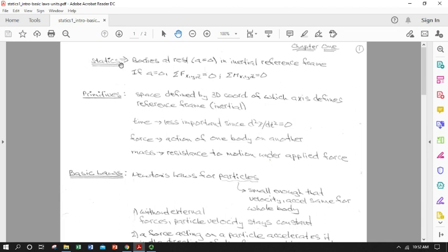Okay, so let's start out with the definition of statics. What is statics? Because engineering mechanics typically includes three different disciplines: statics, dynamics, and mechanics of materials. Statics concerns itself with bodies at rest. And this means the physics definition of rest, where acceleration, here A equals 0, is always the case. So the sum of the forces is always going to equal 0. It's not going to equal MA in this class because A is 0. That really simplifies our mathematics and our analysis in almost every case.